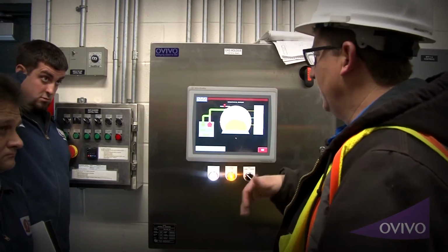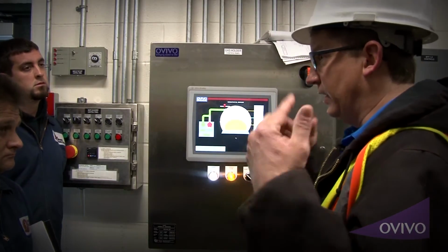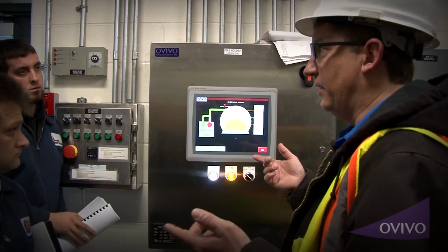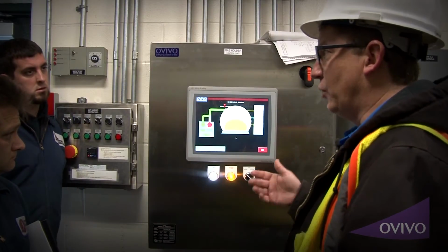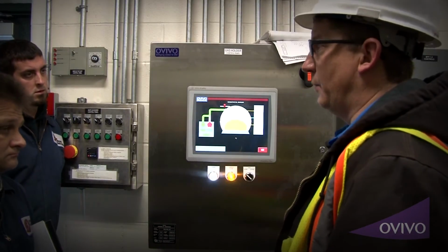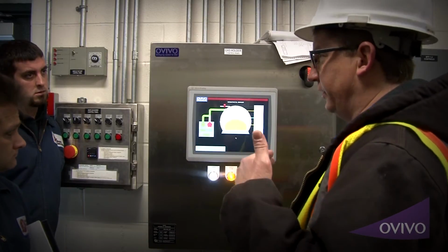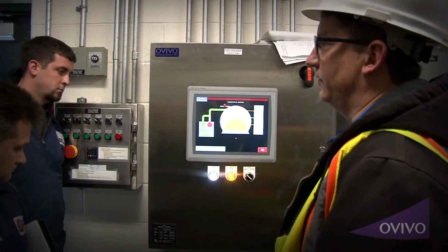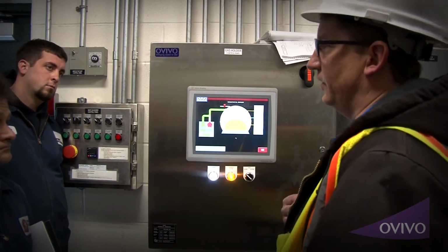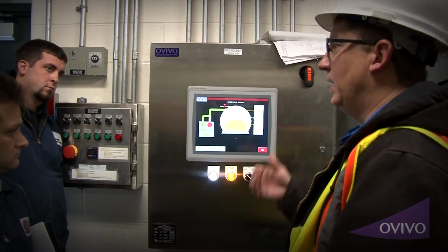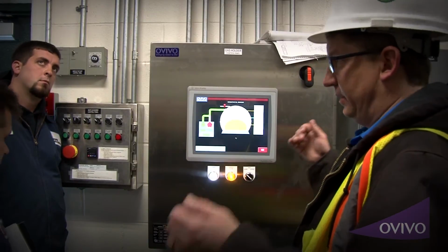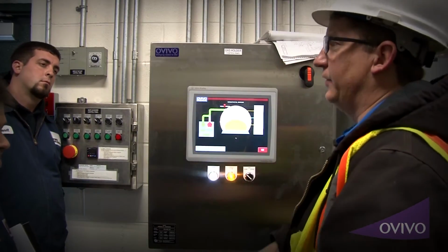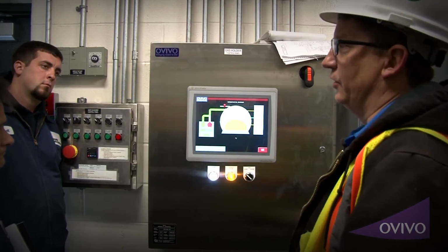You'll leave the fans on because you want to try to cycle out as much of that methane out of the membrane as possible. And from that point on, give us a call. We'll work out a possible scenario depending on what the situation is at that particular second. It's hard to say what you would do, because it depends completely on the situation. But the first thing you would do is drain every ounce of gas you can out of it and put it into purge mode.